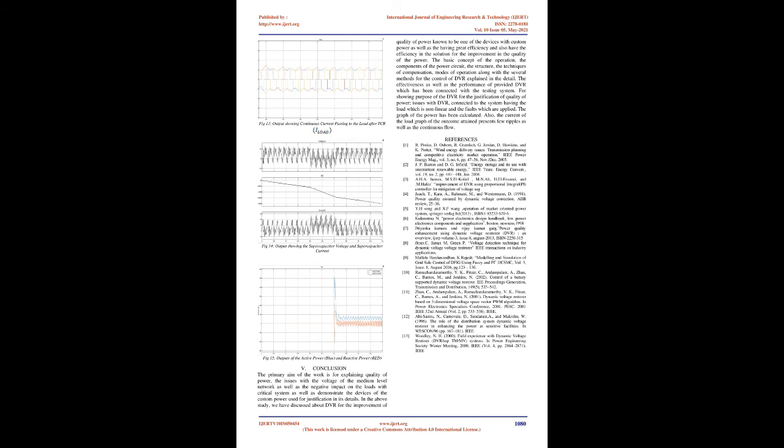From Fig. 4, the bus voltage V can be expressed. V can be varied if the delay angle is controlled. What it implies is that V can be varied, and the generation of the voltage sag by thyristor switch firing of the TCR, as well as the extreme voltage drop, is decided by the ratio between the inductances, under the provided load conditions.